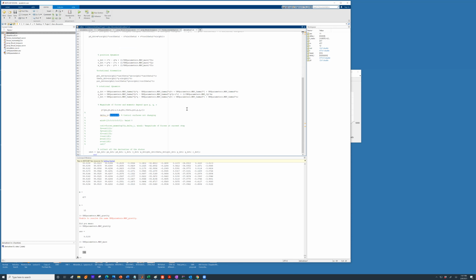So now next thing is I want you to look at the wind. For this initial simulation, I'm going to assume the wind vector is equal to 0. So delta I are nothing but the first 3 are the deflections of control surfaces. For initial simulation, I'm going to keep it as 0.